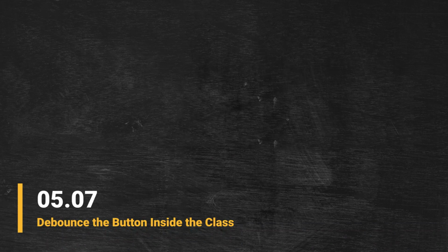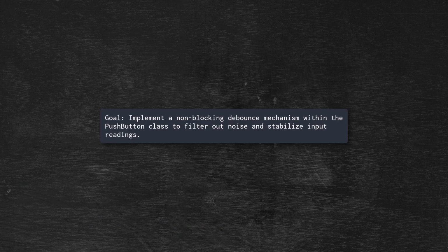Welcome back. While our push button works, hardware buttons have a physical flaw called bouncing. When you press them, the metal contacts bounce rapidly, causing the Arduino to see multiple presses in many milliseconds. Today, we will fix this by implementing a debounce mechanism directly inside our class.